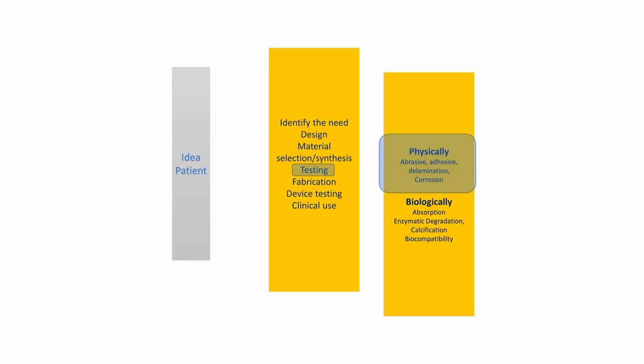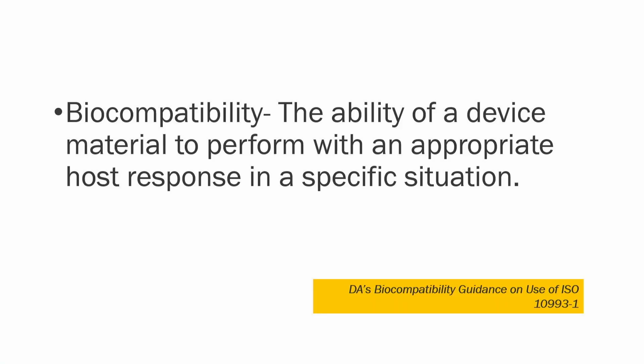From a physical standpoint, you're looking at abrasive, adhesive, delamination, or corrosion based difficulties, along with tensile and compressive strengths. From a biological standpoint, you're looking at absorption, enzymatic degradation, calcification, biocompatibility. So these are some of the things to consider, where you would find further metrics to evaluate whether these are working fine or not, right? Makes sense? Okay, so let's formally define biocompatibility as per the ISO norms, right?